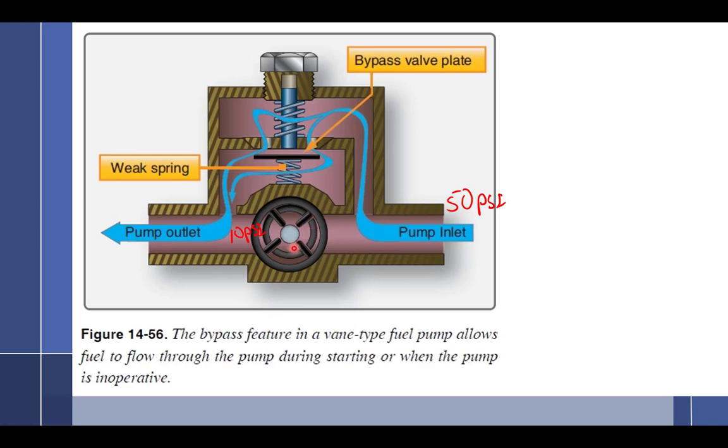So this question: if after the main pump there will be two small orifices, the main pump will increase the pressure and the boost pump will increase the pressure. Okay, so you're saying if I have a very small orifice right here, will the pressure start going up? Yep. No, because this right here is going to open up. And under most circumstances, this pump here is usually more powerful than the boost pump, because the boost pump is centrifugal, or not constant displacement, at least.